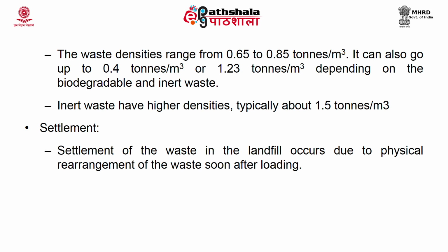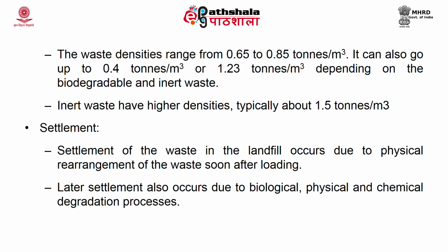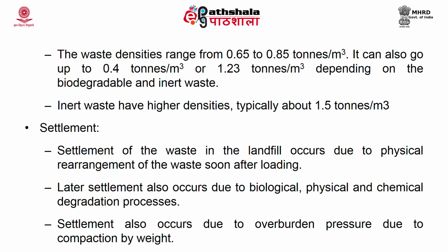Now, settlement of the waste in a landfill occurs due to physical alteration, physical rearrangement. That means, for example, if the waste is loose and has a lot of void space, slowly due to the weight of the overlying waste or when a truck moves over it, automatically the void space gets reduced. So, that is called physical rearrangement. The settlement can occur due to physical rearrangement or due to biological, physical or chemical degradation processes, which will also lead to settlement. The settlement also occurs due to the overburden pressure, which I told you a couple of slides before.